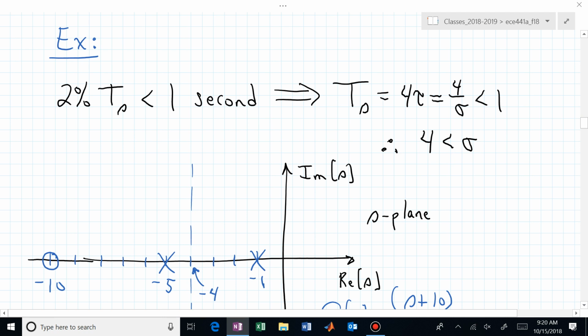You know T sub s, the settling time for a what? For a 2-pole system. Here we're assuming that the 2 poles that we're focused on are dominating our behavior. So if you had a 10th order system, you're going to focus on the 2 dominant poles. If I have 10 poles spread out on the complex S-plane and they're all stable, that means they're all where? In the left half plane.